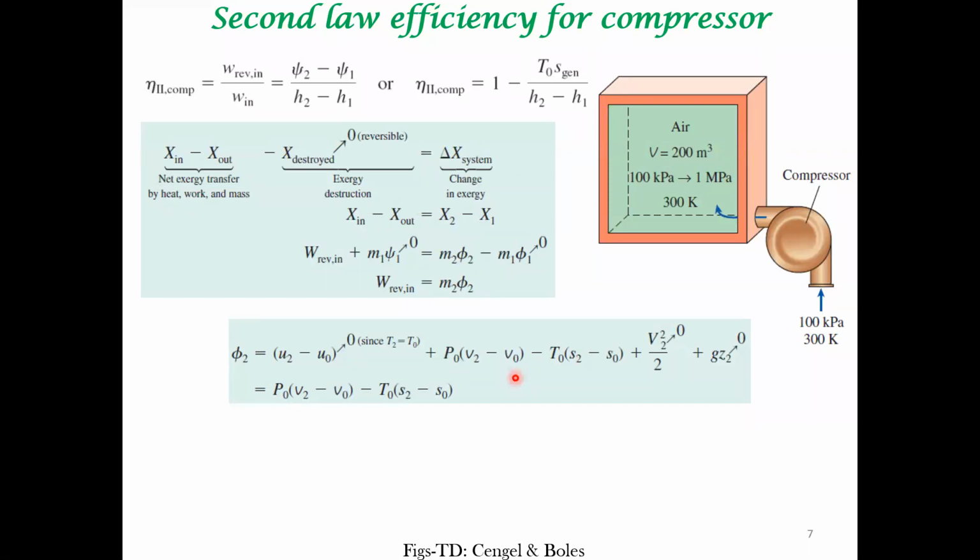So what does a compressor do? A compressor just increases the pressure. If you look at the temperatures, the inlet fluid is at the atmospheric temperature. Even in this enclosure, the temperature is only 300 Kelvin. Therefore, this term would be zero because T2 is the same as the external ambient temperature. But what is changing is the specific volume. As the compressor operates, the specific volume decreases.